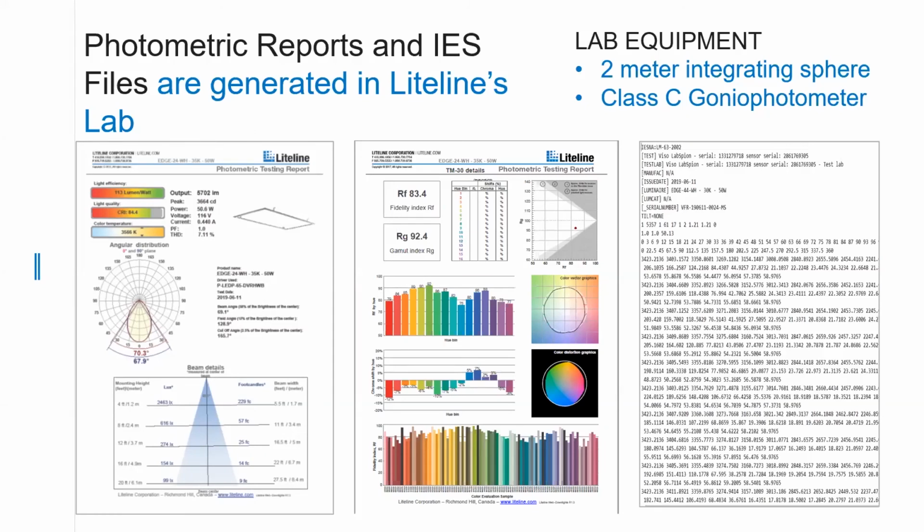And the reason for that is that phosphors have to be layered onto an LED in order to create higher CRI, and color temperatures also have to be scrubbed out. So the blue content has to be scrubbed, so more phosphor is layered on. That's why lower CCT sources are less efficacious than higher CCT sources. Anyways, now on to photometric reports and IES files.